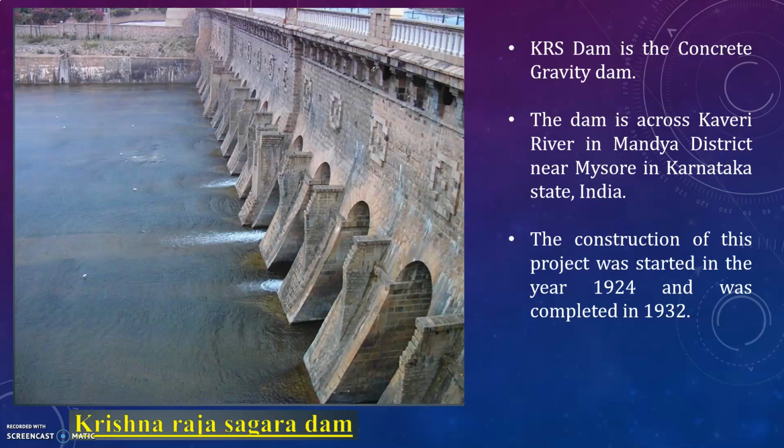A gravity dam requires the least maintenance. The failure of a gravity dam, if any, is not sudden. It gives enough warning time before the area on the downstream side is flooded due to damage to the gravity dam. On the contrary, an earth dam generally fails suddenly. A gravity dam is cheaper in the long run since it is more permanent than any other type. Thus, the benefit cost ratio of such a dam is always higher.